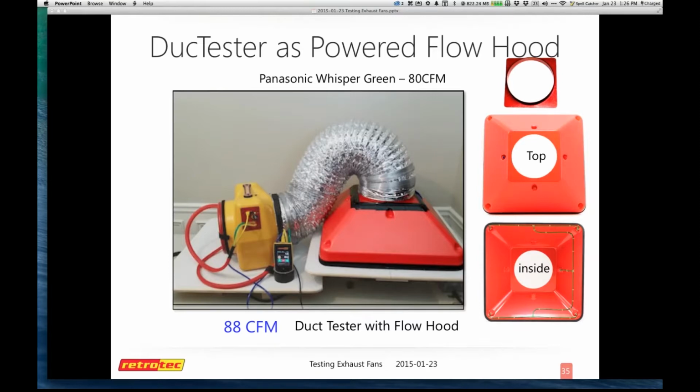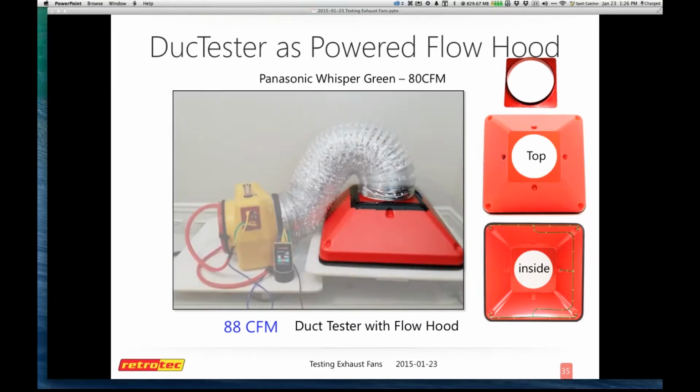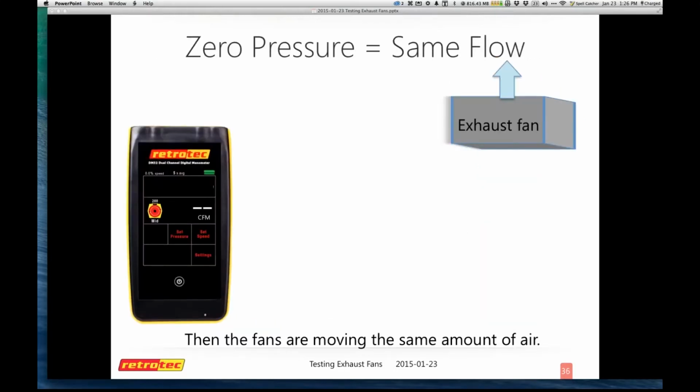So what I'm trying to do is just match the pressure inside my flex duct, basically, in a neutral area that's going through. So my exhaust fan, then I can actually take the red flange, or the flange you use for the DucTester. I'm going to make that connection, and I'm going to get the blue tube to be reading the pressure that's in this area. And it just cannot be in the direct flow. It has to be some type of passive pressure device, or even just kind of covered so it reads pressure without actually having airflow into it.